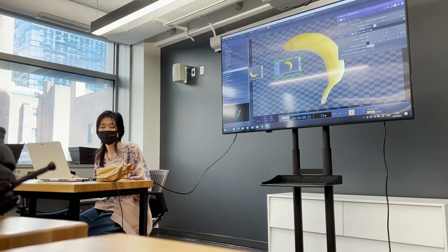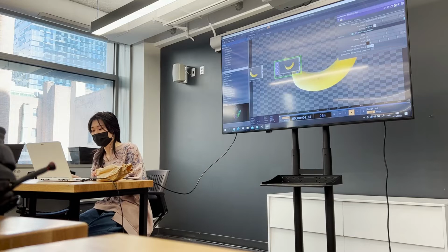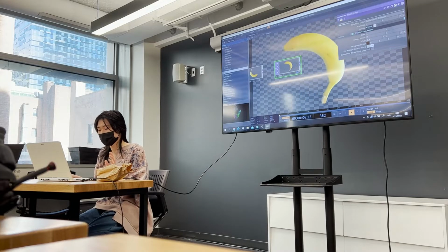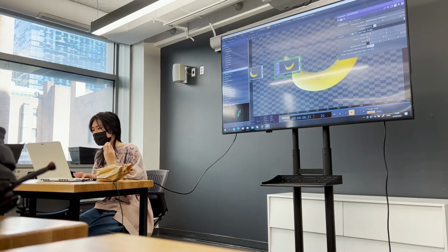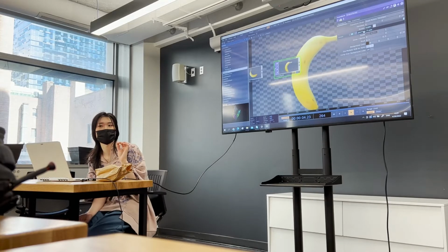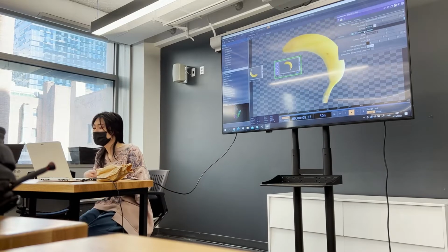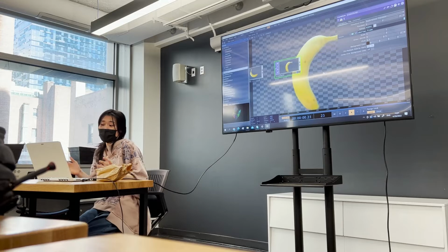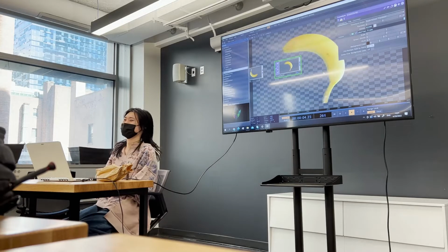And see down here, the frame is also going up, but now the timeline is set between frame 0 and 600, so it's going to keep looping. But this absTime.frame is not going to loop because it's the absolute time since the opening of this project. So you can see this banana is spinning, which is, I don't know, pretty ideal.